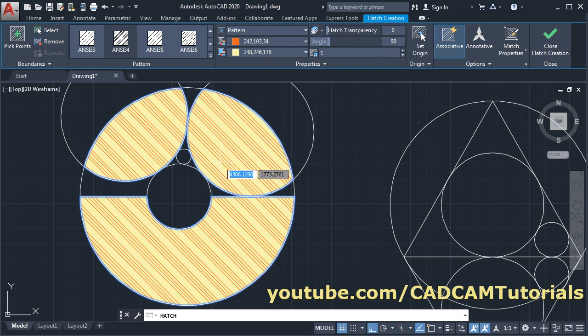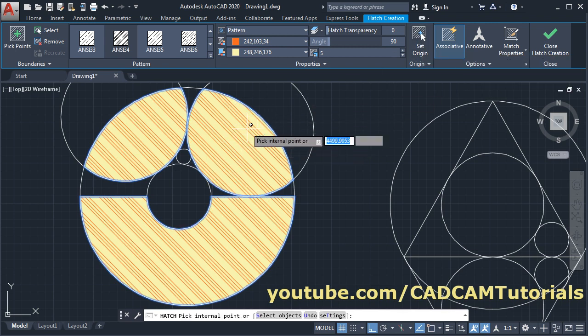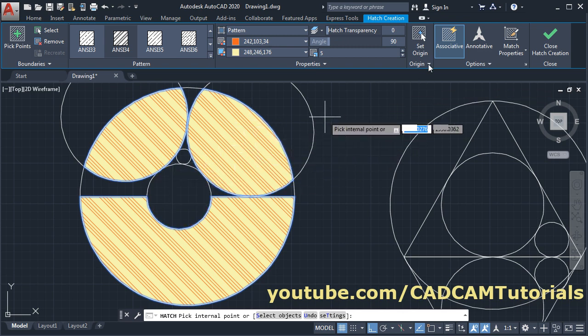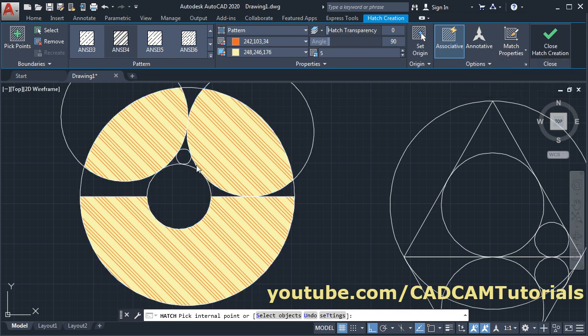If you are not happy with the layout of the lines, you can set the origin also. Click on it, and suppose I will give the origin here. So here you can view that the lines are shifted. So just click on set origin and give the origin. So in that way you can shift the pattern also. Once all your settings are done, then click on close hatch creation. So that hatch will be created.